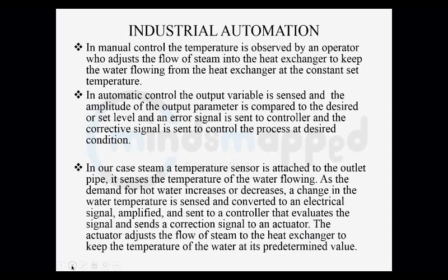The sensor is constantly sending the temperature to your controller as an input. So when the temperature goes below range, the controller will receive this input and evaluate it as per the logic that is written there.